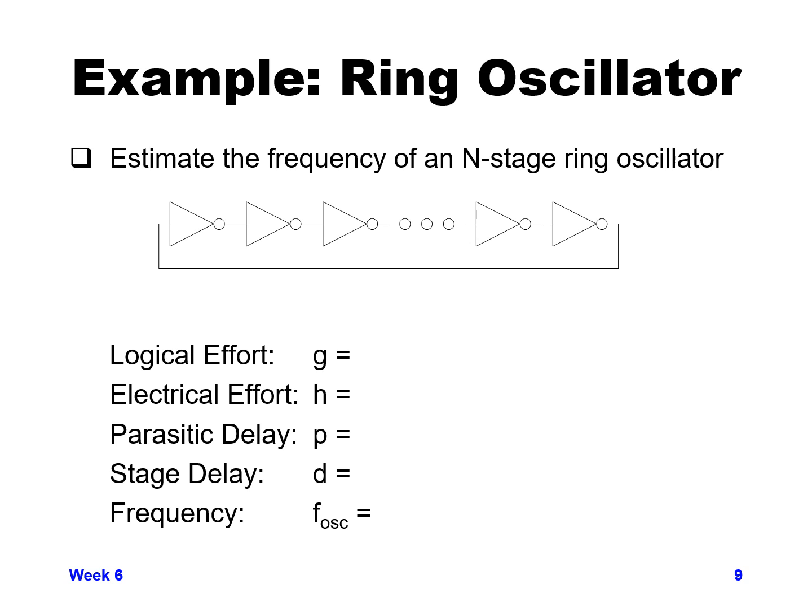Hopefully you've figured it out. Let's go through and determine each of the values here. Our logical effort, G, is 1, as with basic inverters. By definition, G is 1. Electrical effort is the fan out. In this particular case, each inverter is just driving one other inverter, so H is 1. Parasitic delay for a basic inverter is 1, so our overall delay is going to be G times H plus P. That gives us 2, so the delay through each stage is